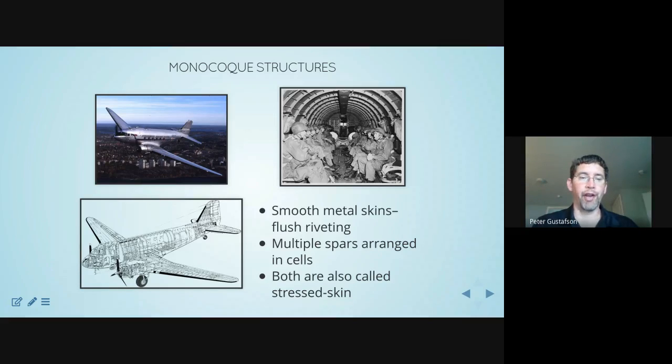So the next big advantage that began to occur, and this is relative to the trimotor, where the skins of the aircraft were not designed to carry much load, was the structural innovation to what is called a monocoque structure, or perhaps a semi-monocoque structure. Now, some examples of early aircraft that took advantage of this feature, the DC-3 is one of those aircraft. That's what's shown up here in the top left. In fact, schematically, its structure is shown in the bottom left.